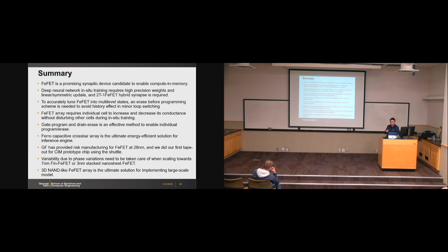But still, we have some challenges in terms of variation control, and also the individual cell programming and erase in the array setting. So we have come up with some solutions from the peripheral circuits and biasing scheme. And also we propose a new way to do in-memory computing, that is, using capacitive readout instead of resistive readout.